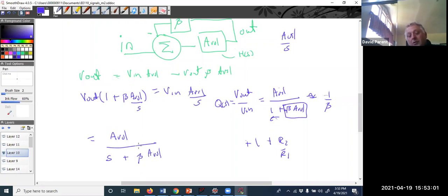And now you could say open loop gain goes to infinity. The S drops out. But what really is that condition is when beta times open loop gain is much, much bigger than omega. That's when open loop gain will appear to be like infinity. And then it cancels out and that drops out and you're left with 1 over beta, right?